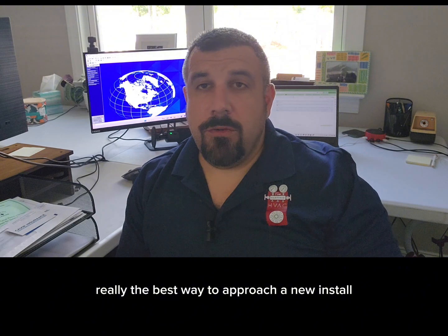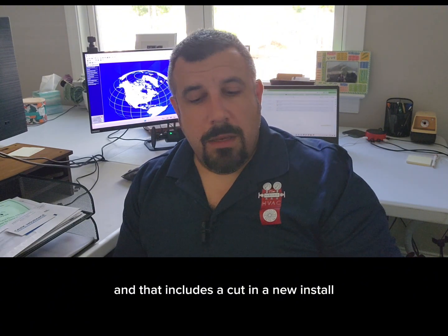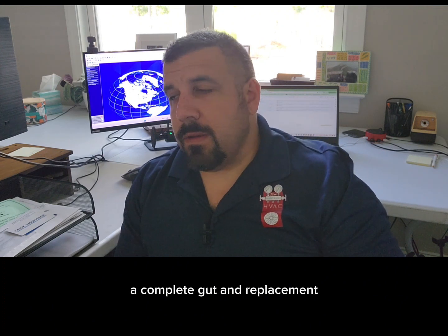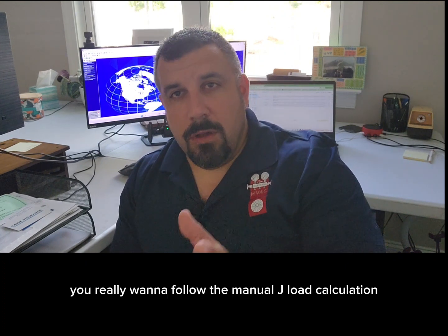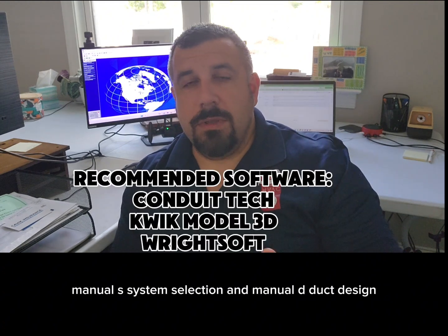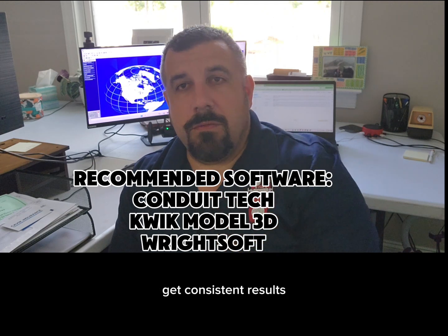Really the best way to approach a new install, and that includes a cut-in, a new install, a complete gut and replacement, anytime that you're doing an entire system, you really want to follow the Manual J load calculation, Manual S system selection, and Manual D duct design. That is the best way that you're going to get consistent results.